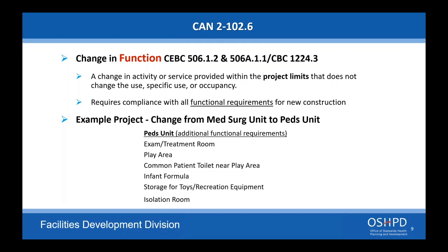A lot of the questions we get are about the pre-balance report before you do that. If you have an HVAC unit that's not running, you can't balance the air because there's no air coming out of it. What you have are a couple options. If you have the original design drawings for that, you can balance it to the original design levels.